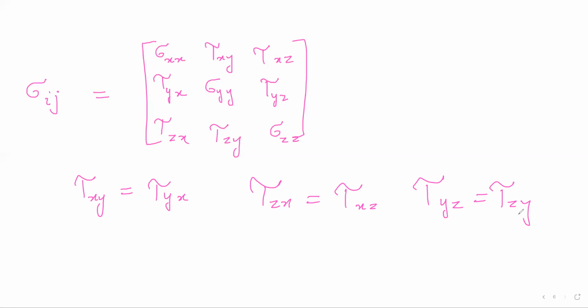When you use the word solution, that has to be an equation. Yeah, that's my point, that we will talk about solutions to it. But right now it's just a stress tensor. So I'm applying a general loading to this one. If I tell you what is the situation of stress at any random element when I'm twisting it, or probably you have that board right in front of your university, this board with this rod, and there are these boards for directions, right? So when wind flows over it, you have that whole rod that wants to twist, because when the air falls on the board, it wants to turn. But at the same time, when the wind is falling on that board, this whole rod wants to bend as well, right? So at the end of the day, if you take out any cube from that solid rod and you start to look at it, there will be in general 9 stress components.